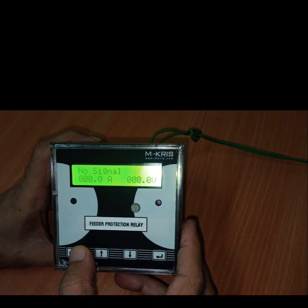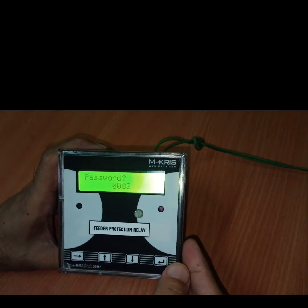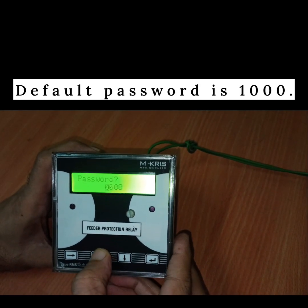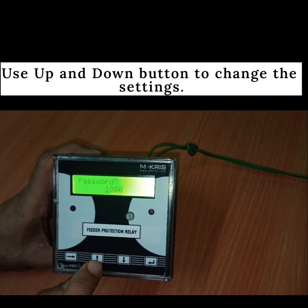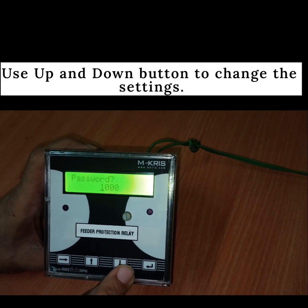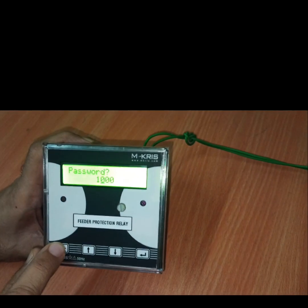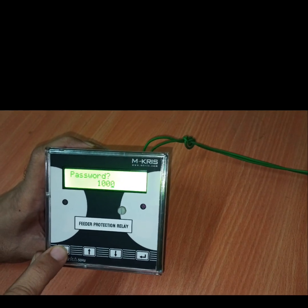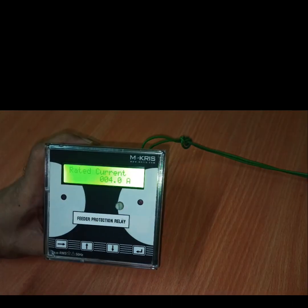Now we go to how the settings are made and what all settings are available. So the settings are protected by a password. Default password is 1000. So 1000, using up and down we can increase and decrease the value of individual digits. As the password is 1000, we will just move ahead. So password is okay. We move into the settings.